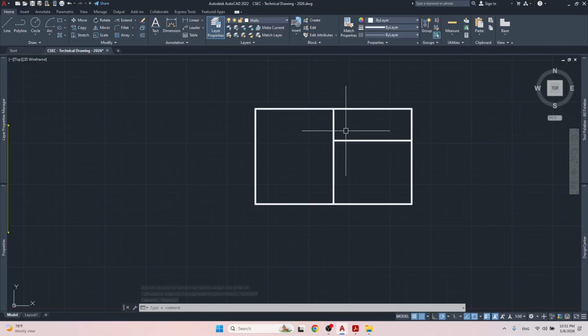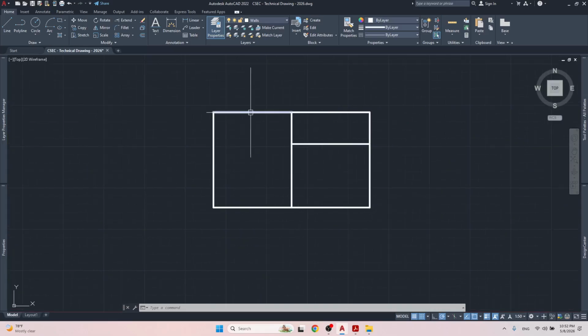It's 1200, right? Good. This should run all the way across. So basically underneath all of our load bearing walls, you're going to have a foundation wall and then a footing underneath that.